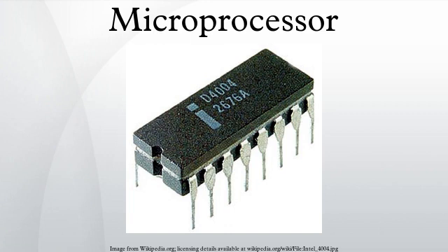Motorola's success with the 68000 led to the MC68010, which added virtual memory support. The MC68020, introduced in 1984, added full 32-bit data and address buses. The 68020 became hugely popular in the Unix supermicrocomputer market, and many small companies produced desktop-size systems.